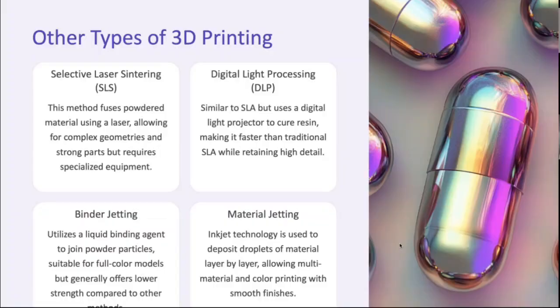Okay. So in this way, this material jetting technology will be used. In the same way, you can even print metals in binder jetting and SLS also, but they won't have as much strength as material jetting will have. In material jetting, the metal is bonded by using a torch or some melting process. But there, a binding agent will be used, which won't give proper bonding between layers, so that will have some drawbacks.